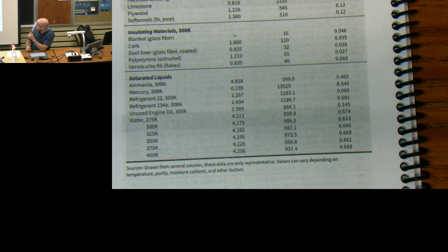Okay, so that's the first thing. It is a closed system. This tank's not moving anywhere, and it's not changing its height, so its kinetic energy and potential energy effects are negligible. In this system, there's no electrical work, there's no mechanical work. Again, you can make the argument that the boundary is going to change a little bit when that 1 pound of iron goes in, but it's going to be so small that we don't have to worry about any boundary work. Let's not worry about that small value, and let's take care of this work and get rid of it.